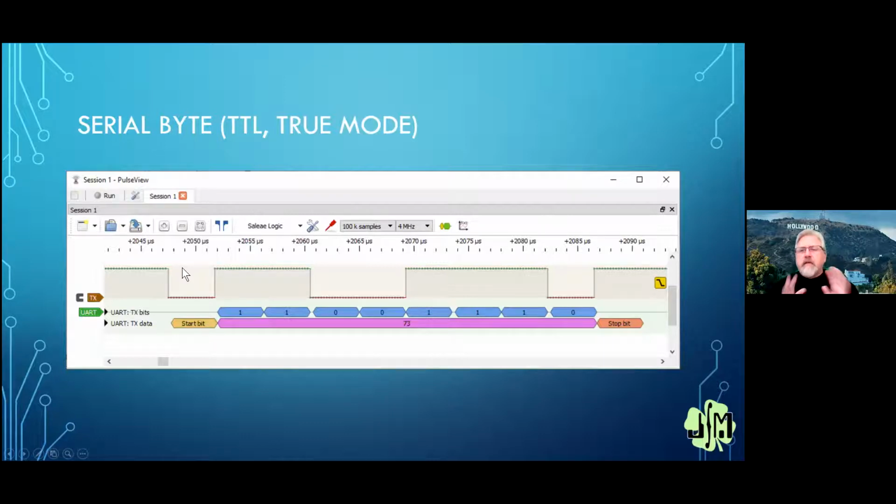That seemed to be the sweet spot, that or higher. You don't want to have it be interrupting too much, or else you never get anything else done. And that would allow the generation and the receipt, because if you're not able to detect the start bit exactly when it came in, because it may already be in a start bit mode when you hit the interrupt, that amount of resolution gave you the ability to do that. So it's much nicer in the Propeller.